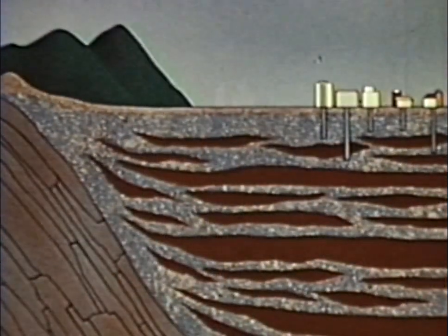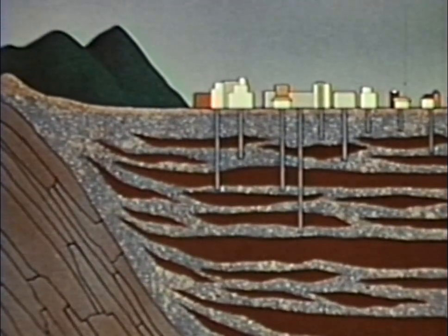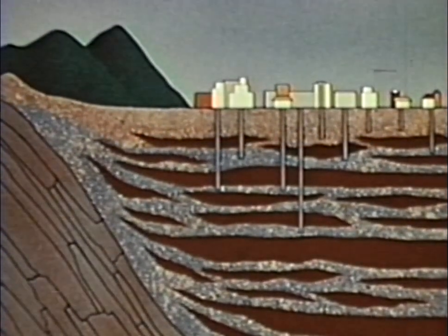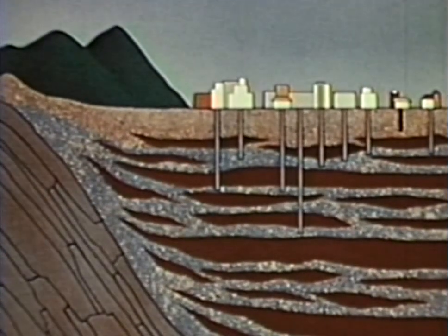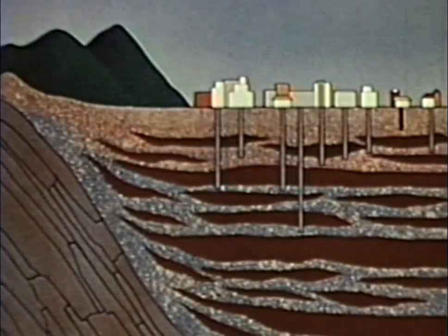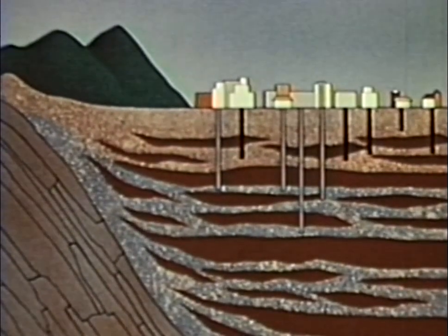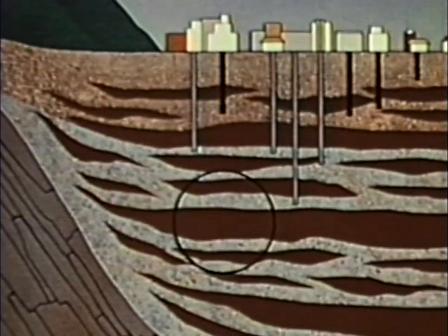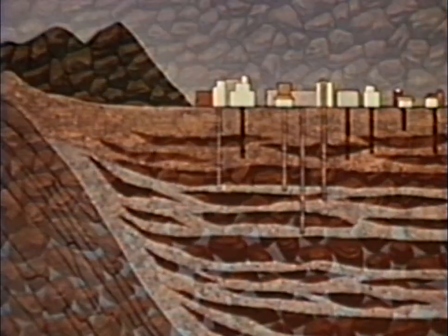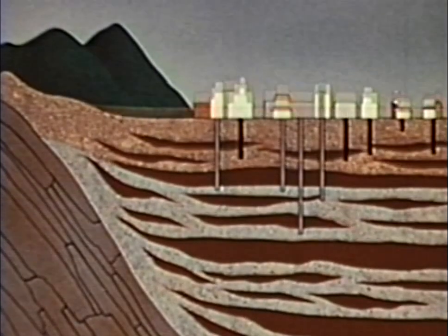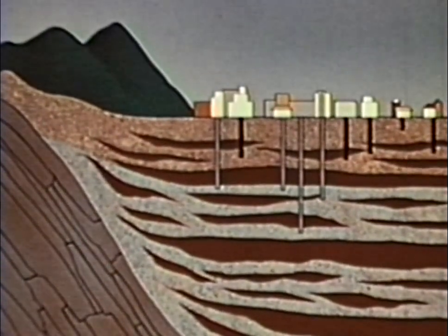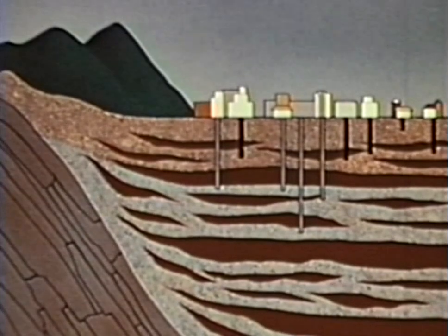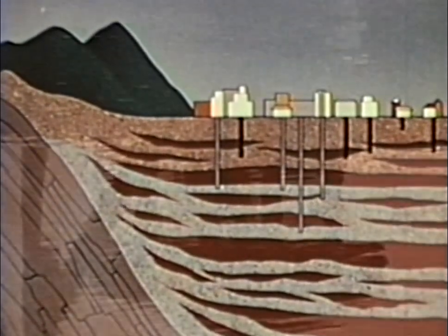When aquifers are excessively pumped, the water table is lowered, causing shallow wells to go dry, shown here in black. As pumping continues, water levels decline further, and deeper wells go dry. As the groundwater pressure is reduced, layers of silt or clay in the aquifer system are compressed. This compression causes the land surface to subside. This has happened in many places: California, Louisiana, Mexico, Italy.